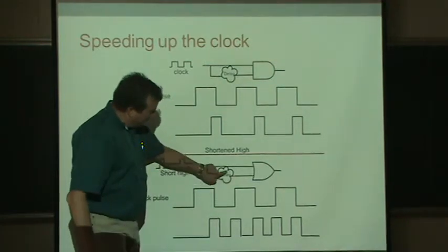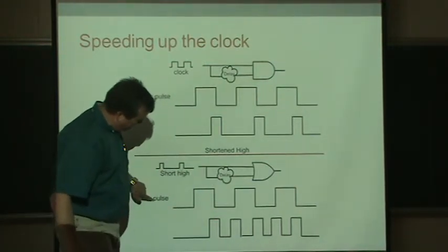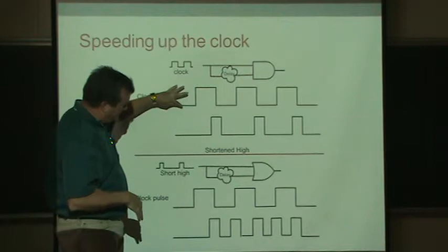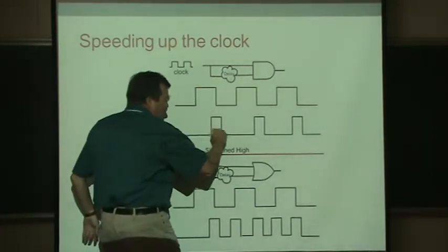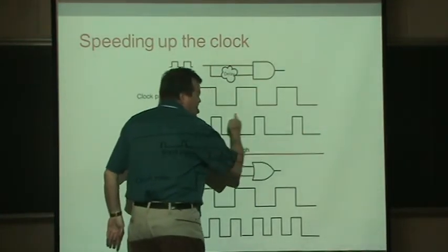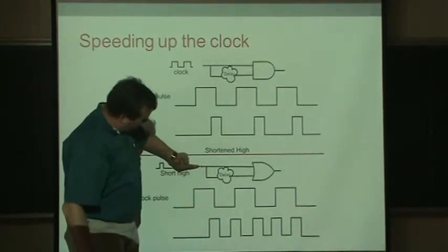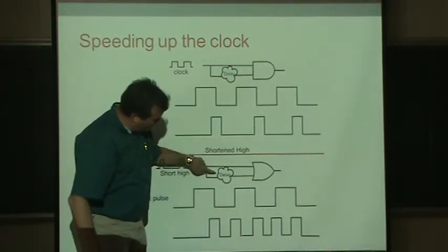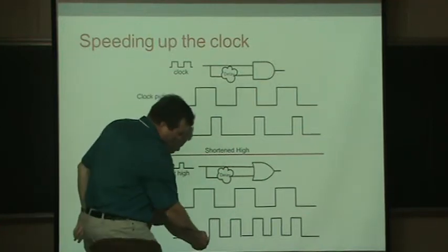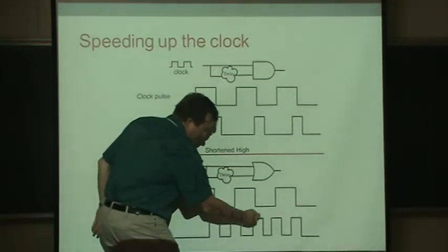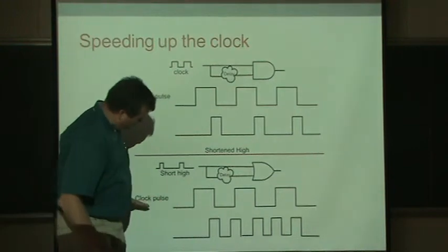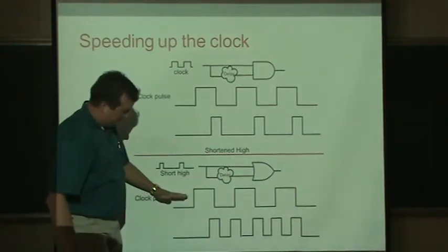Then with this delay, we can take our overall clock input signal, generate this signal, then run 2 of these signals, one delayed and one not delayed, one coming into an OR gate and the other one not delayed, and then we can have twice as many highs from the original input signal.